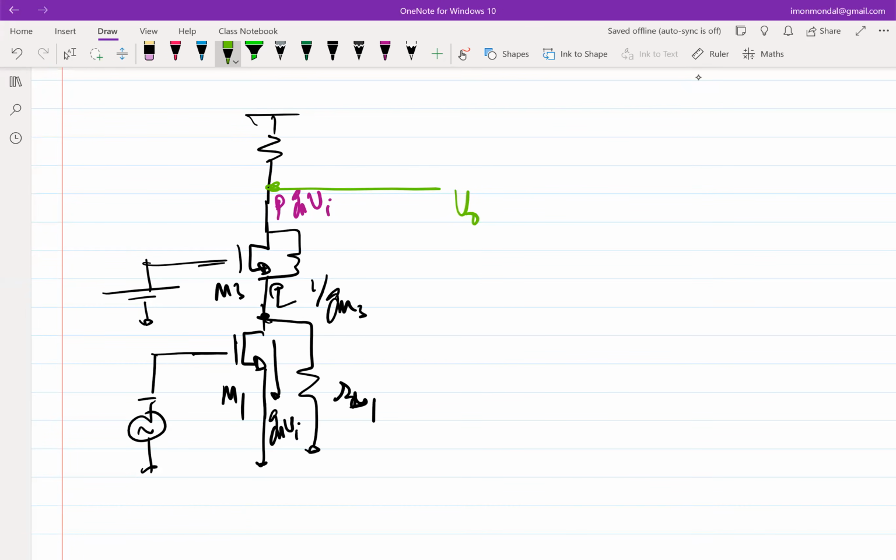Okay. So which essentially means that the question that we are now asking is, I know the short circuit current. The short circuit current is GM times VI, or minus GM times VI in the direction that I have shown. Now I have to find out what is the incremental output resistance looking from that, right? So this resistance is R out of some stage, I know, right? But the key thing is to figure out what is the resistance looking down, right? So what is the resistance looking down? We have seen this structure in multiple contexts. Tell me what is the resistance looking down?